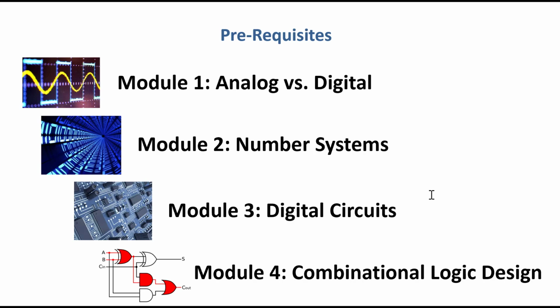So we needed to look at how you create these basic gates in the real world. And so we actually looked at discrete parts from the 74HC series, and we were able to put these parts down on our breadboard and actually build basic logic circuits. Now, when we started building real circuits, we had to consider the real implementation of these circuits. So we had to consider things like power supplies and grounds. These logic gates don't work unless you provide them a VCC voltage and also a ground.